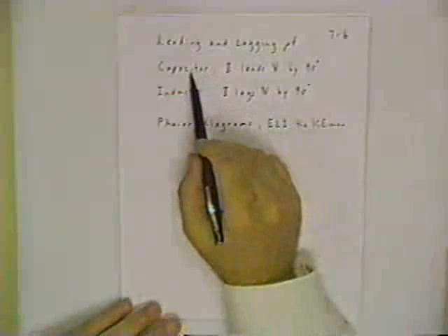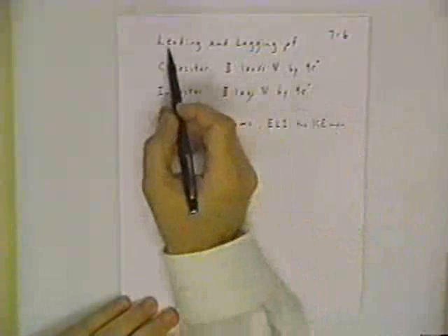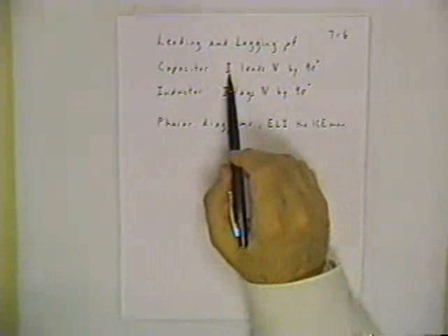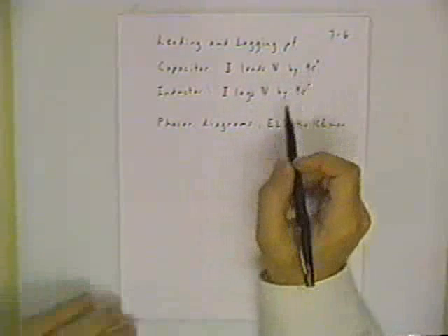So now the question is, how do you use that to interpret some problem statements, and what does that have to do with practical situations like motors, generators, and other kinds of power applications? Well, the power factor tells you if it's a positive or negative power factor. It tells you if your load is more of a capacitive type load or more of an inductive type load. And this gets into the topic of leading and lagging power factors. To illustrate, if you think about the phasor diagram for a capacitor, its current phasor is going to be ahead of its voltage phasor by 90 degrees worth of phase shift.